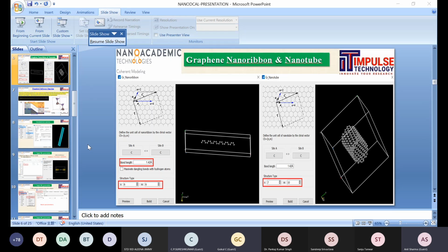And the next option in DFT calculation is called contour integral, where you can set the integral lower bound points, circle points, real axis density point analysis, infinite semi real axis value, and electrode temperature parameter. You can apply the voltage on the left electrode, temperature on the left electrode, k-point number. Similarly for the right electrode. So whenever your device is ready, you need to apply some biasing on that, and based on that biasing, you can find the IV characteristics. So you can apply some biasing as well, and it will calculate the electronic properties and electrical properties.